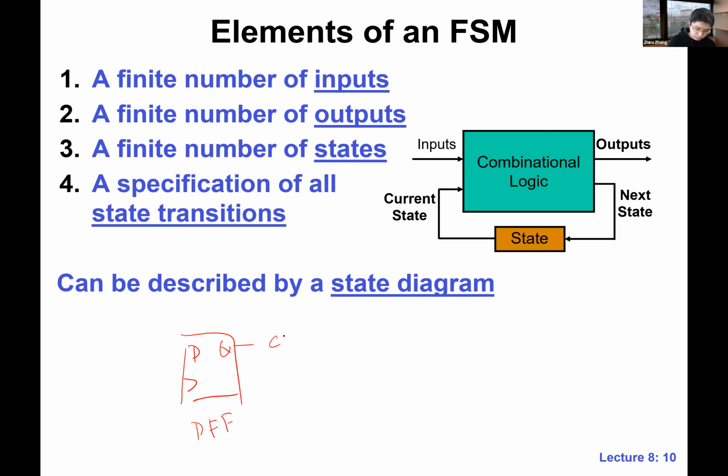This one, this is current. Indeed, right? So this is what Q means, right? Q basically is the thing that this D flip-flop is holding, right? It's current. Make sense? The current state. What is the next state? Which one represents the next state? It should be obvious.